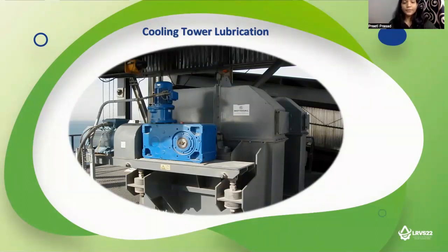Some industries use mineral based oil or synthetic based oil, with viscosity ranging from ISO VG 150 to ISO VG 68, depending on the speed of the fan. Electrical motors are mostly grease lubricated. Smaller motors are sealed for life as they are fitted with ZZ bearings. The larger motors, greater than 75 horsepower, are mostly oil bath lubricated, and ISO VG 68 gear oils are mostly found there.